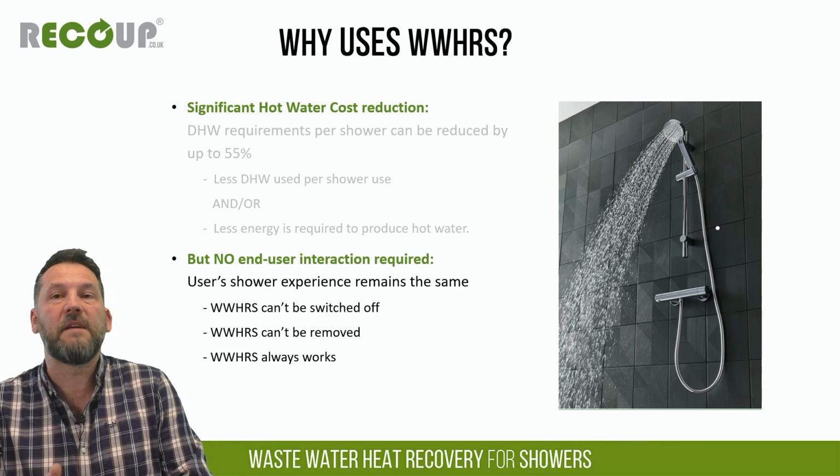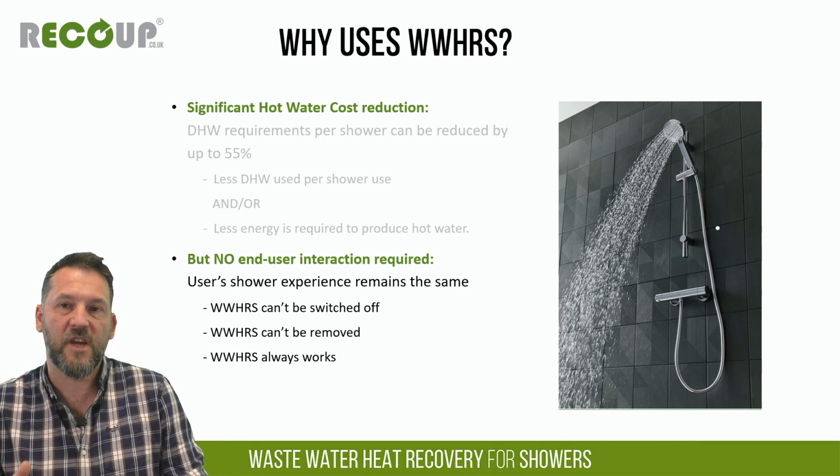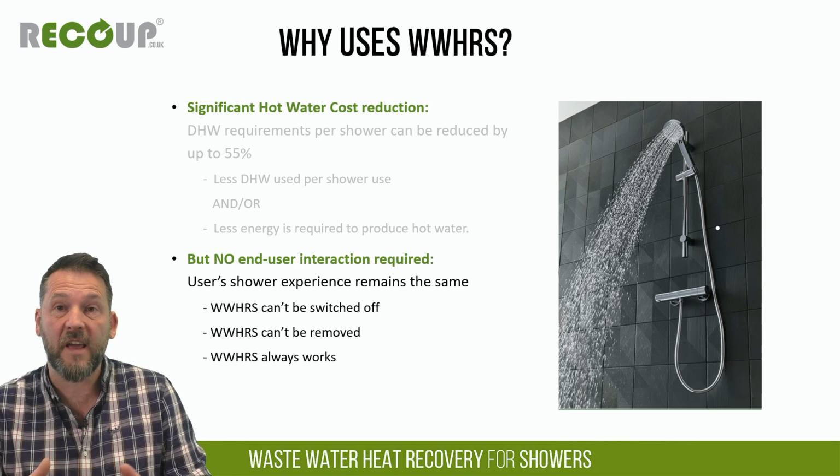And then finally, and very importantly, there's no end user interaction required with wastewater heat recovery. It's a passive heat exchanger, essentially part of the plumbing infrastructure. So it can't be switched off, it can't be removed. It always works every time a shower is switched on. And the shower user, so the end user, really won't see any difference in their showering experience. So for most end users in new build homes, they probably don't even know that wastewater heat recovery is installed. So it really is a very good technology in that respect.